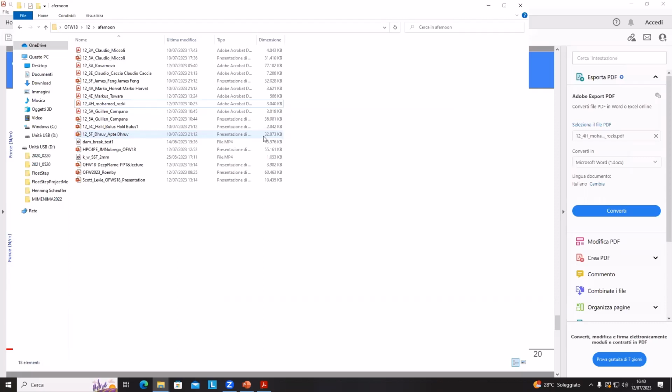Maybe I can add that usually we do not resolve small bubbles and droplets to the sizes when we're doing waves. We don't resolve them to the extent where we can set a meaningful surface tension. There is a surface tension parameter in constant/transportProperties, but it doesn't make sense for this kind of case, unless you have a really fine mesh, but I don't think you do. Yeah, okay, then it could be actually, yeah.